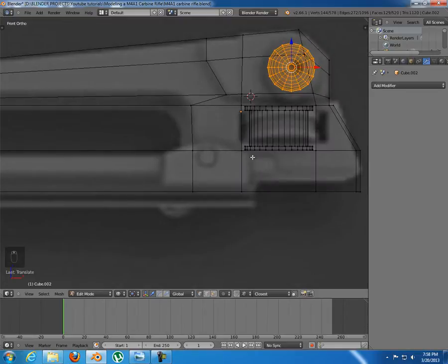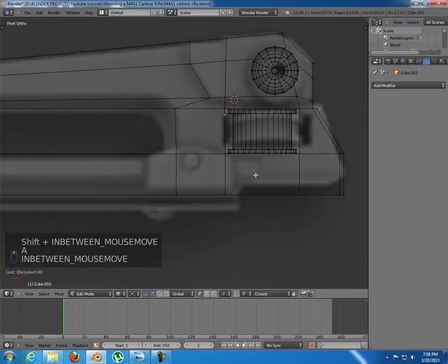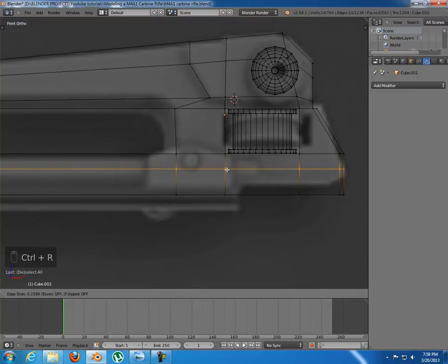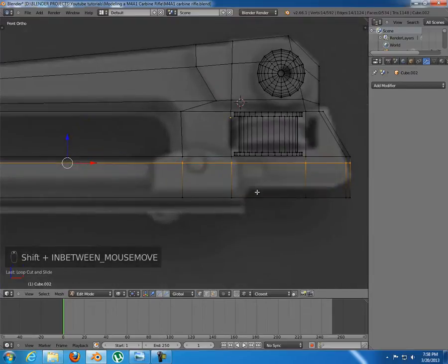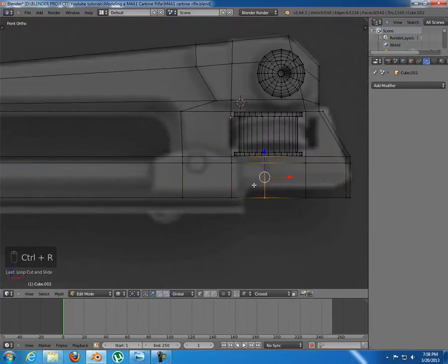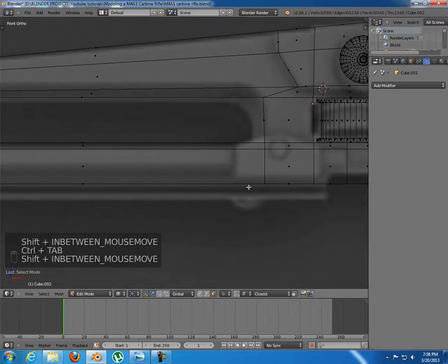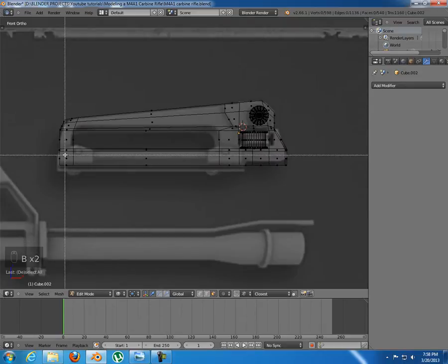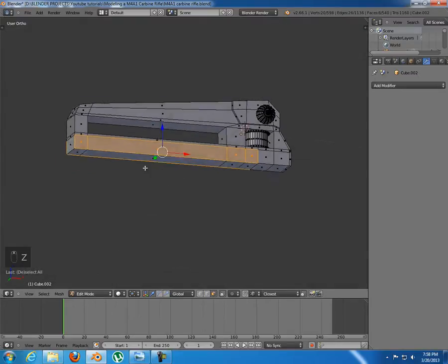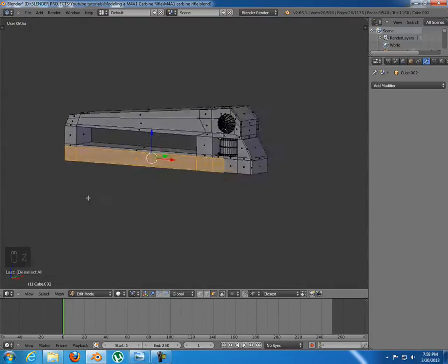So first we see that edge that comes out, or yeah, how you call it. So I'm gonna add a horizontal loop cut in here. I'm just gonna extrude all of that out. Okay, and another loop cut in here. Good. Now into face select mode, box select, and select all of these faces in here on the both sides.